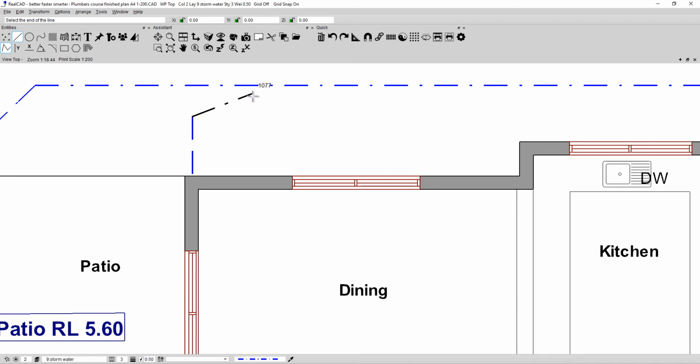I'll show you what I mean and then we'll undo it. So there's my diamond. You can kind of see that. I click and all of a sudden the line jumps at right angles because that's what the diamond does when you are drawing. So I'm going to press undo and that will take me back. I do want my line to come up here at 45, so I'm going to hold the Shift key down.